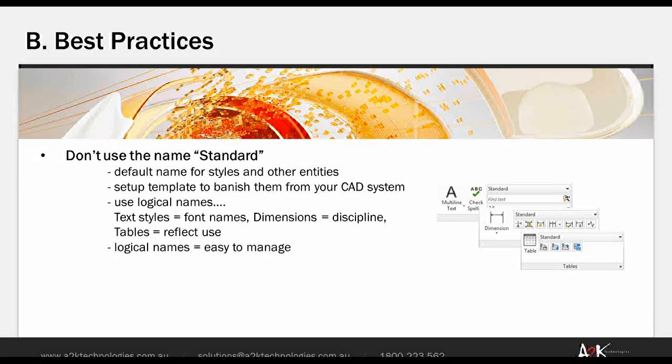All its users will use the name Standard, but they'll go in and redefine the contents of it. And if you insert a block from one drawing to another, and they both have a style called Standard in them, depending on what the object is, the destination drawing will take precedence, and so whatever the setting was in the other drawing will actually get lost.